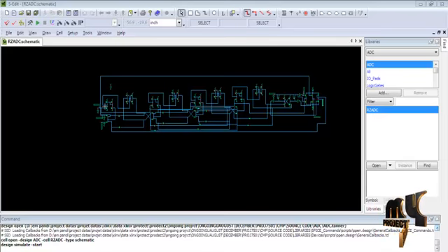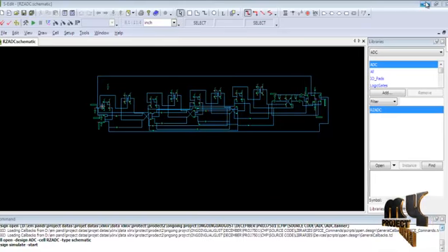This proposed implementation is done in the Tanner EDA tool, in the SEdit tool. First open the SEdit tool and create a new cell. After creating the new cell, we update the library file in the simulation parameter. After updating that, we draw the corresponding circuit as per the base paper. After arranging the circuit, we click the run icon, then the T-space window will open.